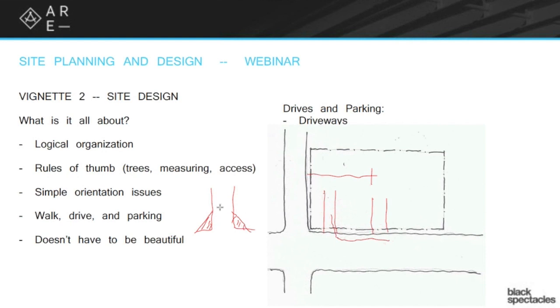And that means that somebody who's parked there getting ready to pull out into the street can see oncoming cars. How big is the triangle? Depends on how fast the street is. If this is a small neighborhood street, the triangle is pretty small, probably maybe 6-7 feet, something like that. If it's a very major street, like an arterial, then I maybe have a much bigger triangle, because I need to see cars going 30, 40 miles an hour.